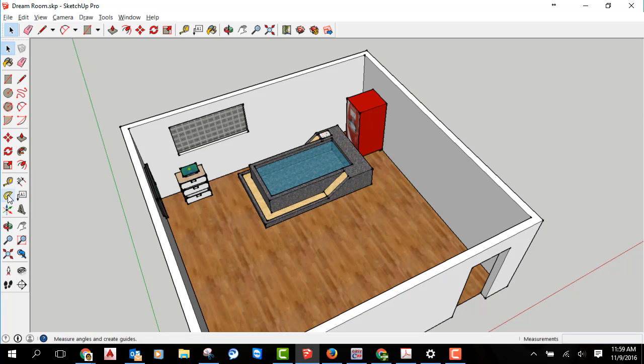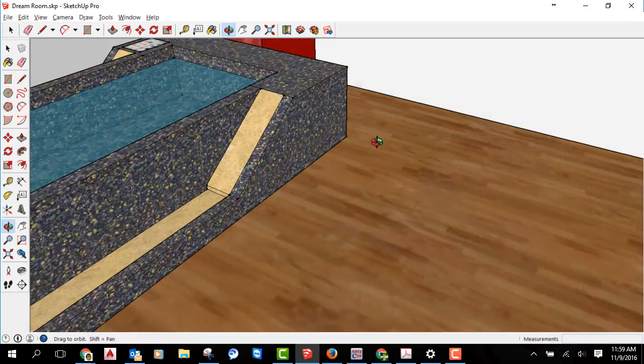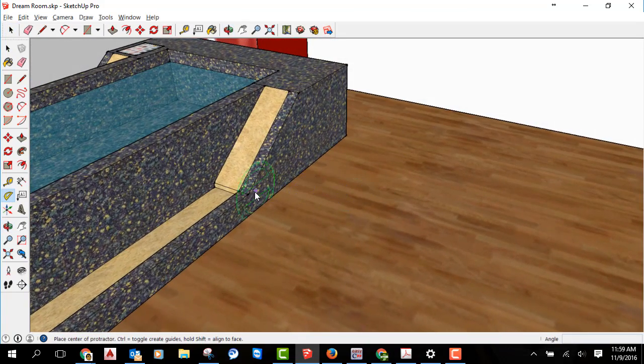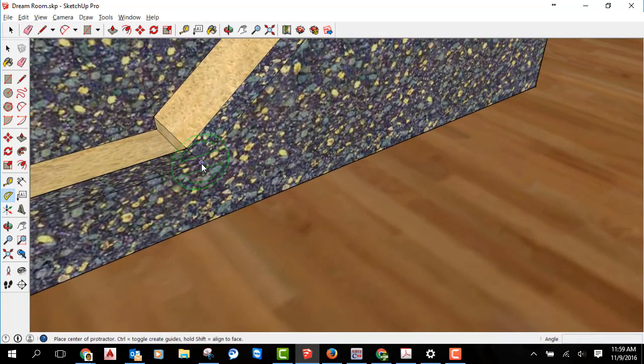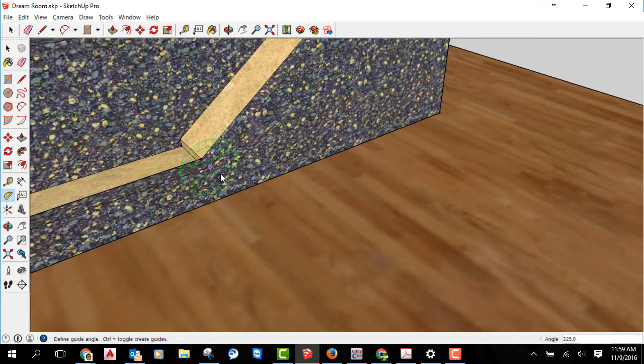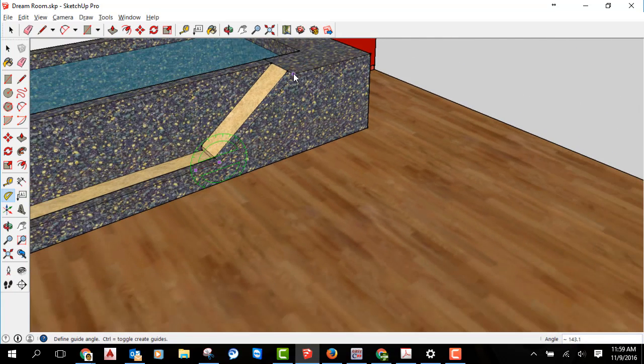We've also got our Protractor. If I click over here, we can see we've got our blue axes. If we're down that way, I'm going to set it up so you can see this. We can figure out what this angle is now that I've drawn it. On the green, I click on one side, and then I rotate to the other. I'm going to go to this corner so it'll actually lock in, and it'll tell me what that angle is.